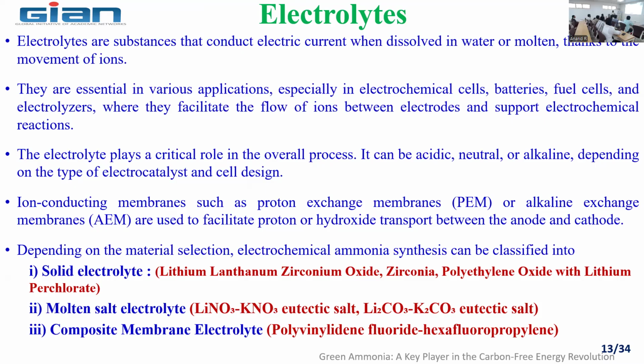Okay, so a catalyst is a substance that only aids in activating the reaction, but does not take part in combustion or anything. So we need to do a thorough literature survey for a proven catalyst. Suppose we are going for new materials, you need to do a lot of catalysis studies. You need to do the TGA study, the XRD study, and some scanning under a microscope to find out the particle size, maybe the porosity, and so on. There are several catalysis methods available to ensure that this catalyst is going to perform better before you take it to the process.